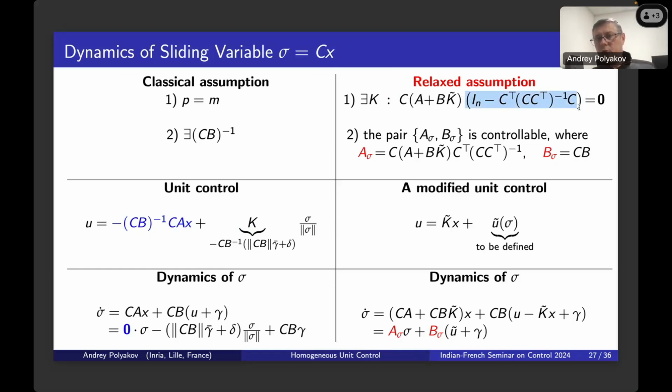In fact, this assumption together with an additional assumption, that the pair formed by the matrix dependent on this k0 and the control inputs for the output variable is controllable. This assumption, in fact, means that the output which we are going to stabilize in finite time to guarantee the sliding mode has to be completely controllable. It means we can design all uncontrollable variables which affect the output completely, so our control may reject them. We can see this in the analysis of the dynamics.